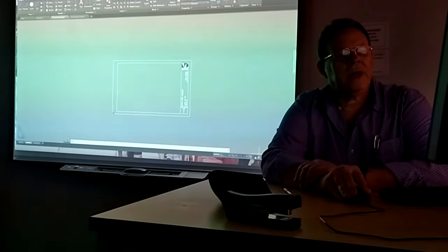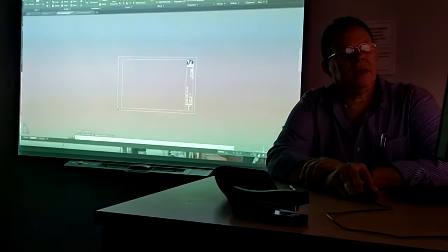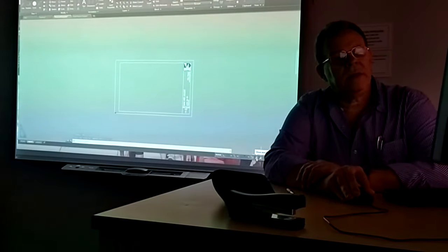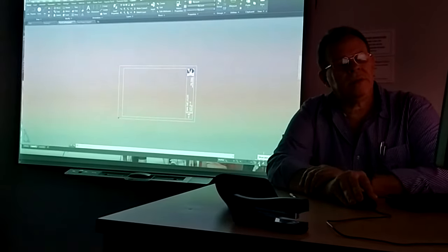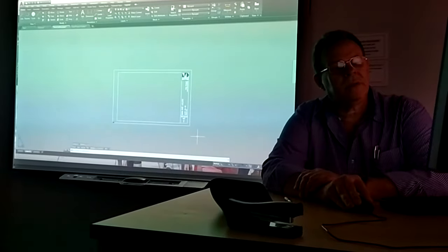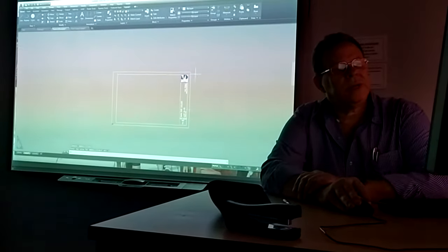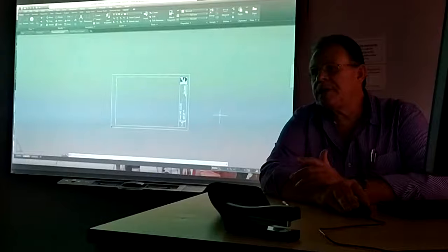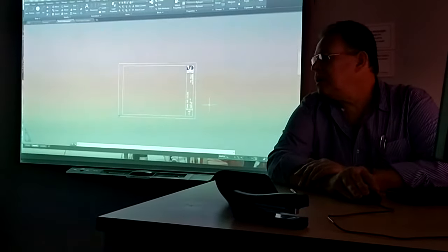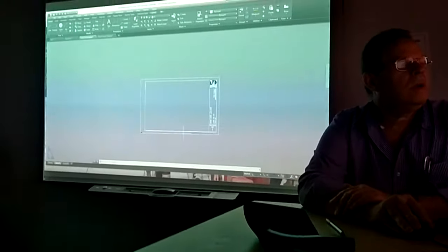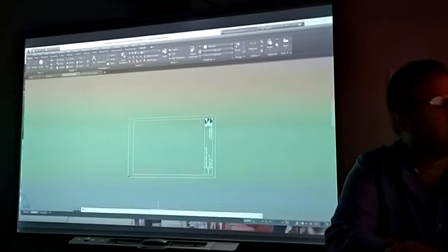You want to make sure that, see, it wasn't lit up. This little show annotation object, the section of the scale, you've got to always light it up. Otherwise your annotation things, your letters, your dimensions, your numbers are going to disappear. Okay, so now this is the trick.